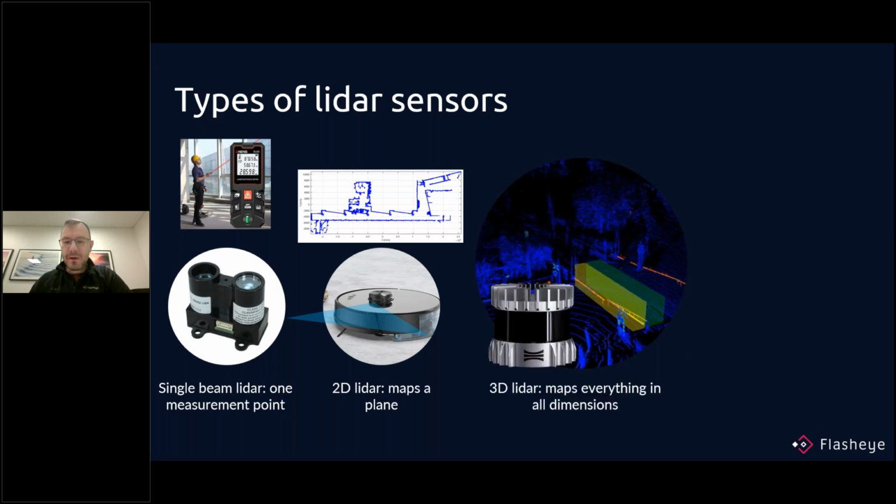Then moving on, we have 3D LiDARs, which are based on similar technology as before, just having multiple of those beams distributed along different angles, and this gives you this three-dimensional perception, because you don't only have one single scan line, you have multiple, from 4, 8, 16 up to 128, and nowadays there is work to introduce even more scan lines with some manufacturers. So this gives a lot of data.